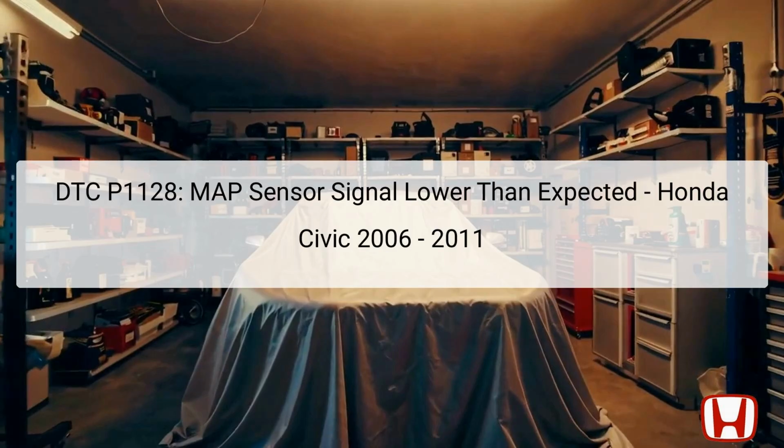The MAP sensor plays a vital role in measuring the atmospheric pressure inside the intake manifold, which helps the engine control module (ECM) adjust fuel delivery for optimal engine performance. When the signal drops below a certain threshold, typically 54.1 kilopascals or 1.61 volts, it triggers this diagnostic trouble code.